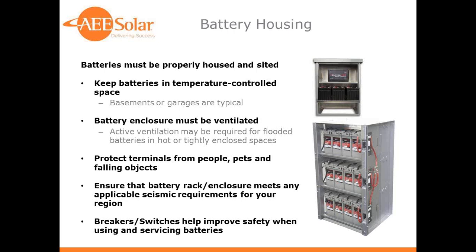Batteries need to be housed properly. It could be a pre-made enclosure, such as we're showing here from a couple of manufacturers. It could also be a built system. Very often battery boxes are built with plywood and lumber. Should certainly be coated with heavy-duty paint. And the battery should either be in a tray or the bottom of the enclosure should be sealed in some way to keep acid spills contained.